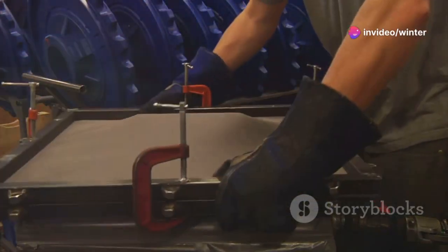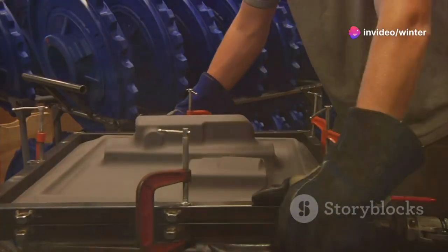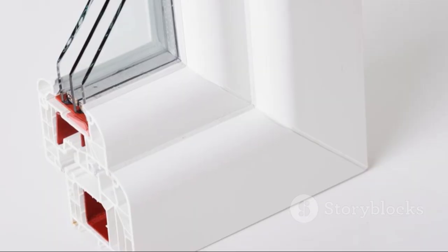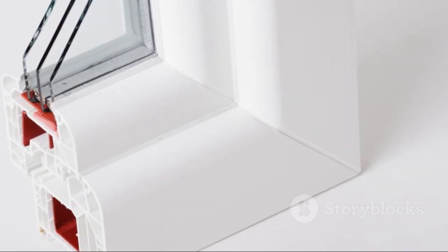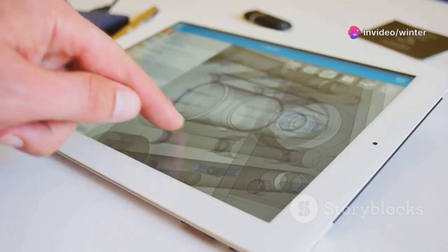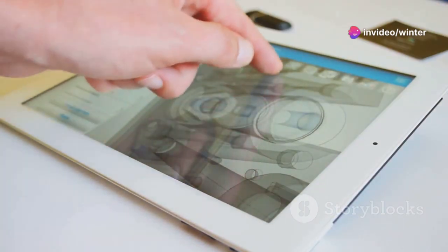Uniform wall thickness is crucial. Thick and thin sections cause sink marks and warping, leading to costly mold adjustments. Consistent walls mean better parts and simpler, cheaper molds. Analyze your design for thick spots. Core them out to match the rest.